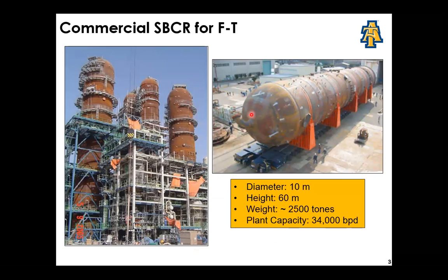In the Fischer-Tropsch process, this type of reactor is preferred to the other three reactors we earlier mentioned because it has excellent heat and mass transfer. It has a low pressure drop, it makes use of finely divided catalysts, and it also has a very high yield per reactor volume. Because of this simple structure, its construction and maintenance costs are quite low.